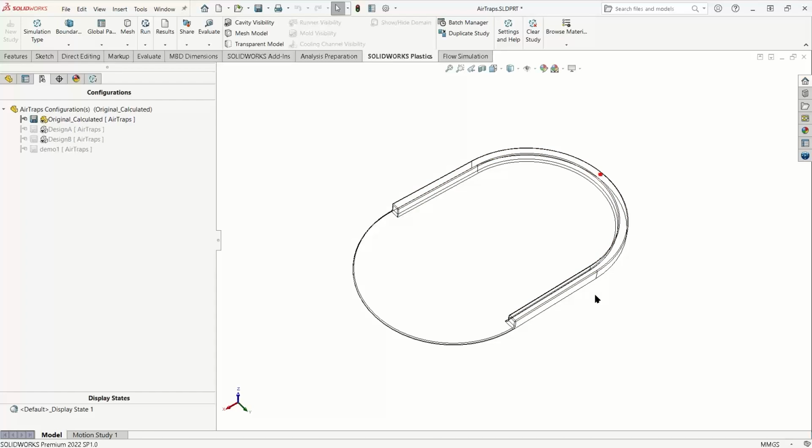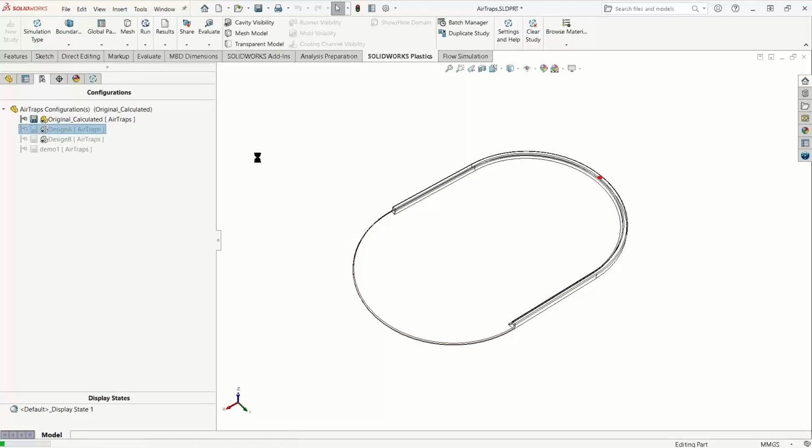So we know that with this weld line, maybe the structure is not good. The stiffness is, we can have some crack for some reason here. So we proposed a new design. Okay, so I'm using a new configuration of SolidWorks where we decrease the thickness of this rib.